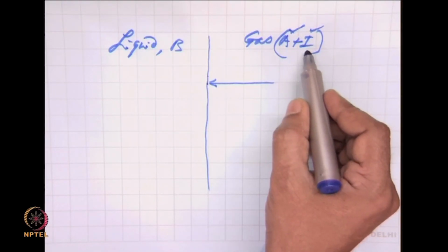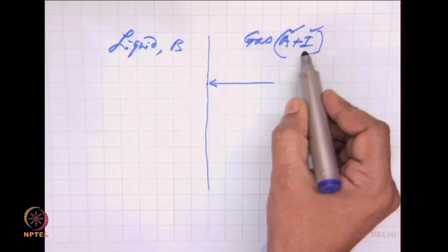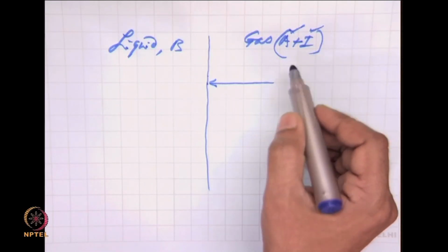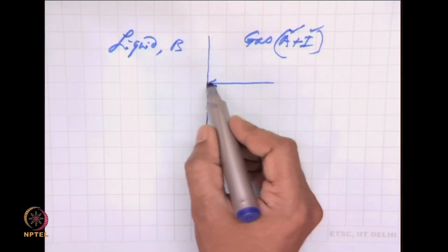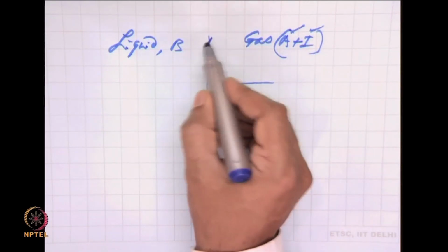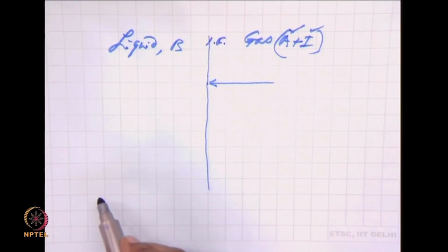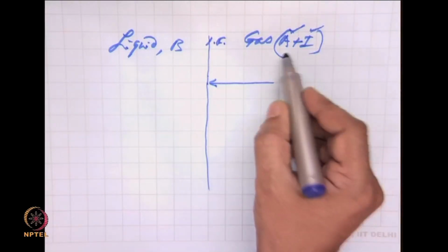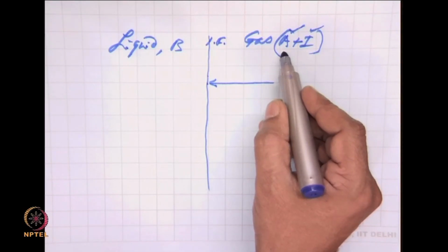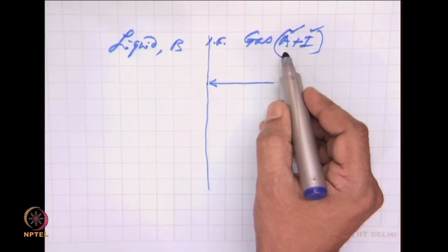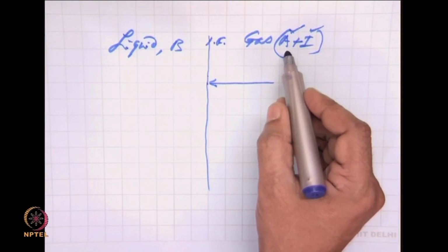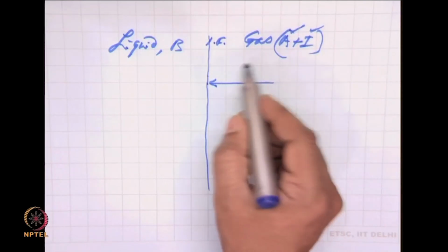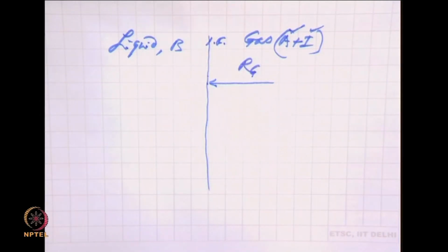Predominantly, if inert is in excess, then most of the intermolecular collisions will be A with I, as far as A is concerned in its path up to the interface. So, the resistance in the gas phase will be highest when the concentration of A is lowest. So, for a very dilute gas phase mixture of A with inerts, the resistance in the gas phase is likely to be significant.